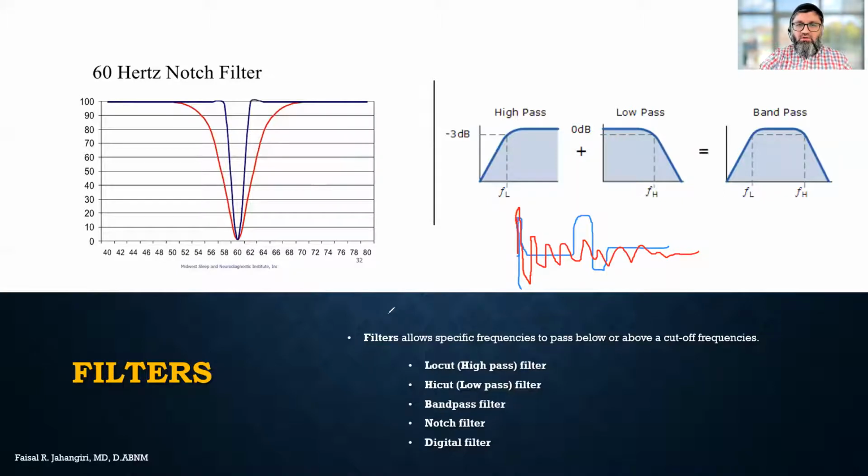The exception is electrocorticography. When we're doing electrocorticography, or EEG directly from the brain cortex, we don't use a notch filter, because spikes or epileptic activity can occur at different frequencies, and using a notch filter in these surgeries may result in attenuation of the signal.